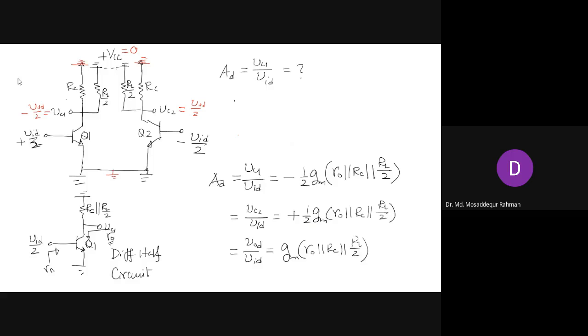There can be high DC voltage, but the small signal voltage is 0 at that point. So that's basically at ground potential, and we can show it like there is a ground at that point. It's already connected to ground, right? So it is like this. You have a point in the circuit that's not directly connected to ground, but probably there is a voltage source. So at this point, you have a DC voltage, right? DC voltage is constant, but AC voltage is 0, because AC means there has to be some fluctuation like this, right? But there is no fluctuation. You have a constant voltage. So that is DC voltage.